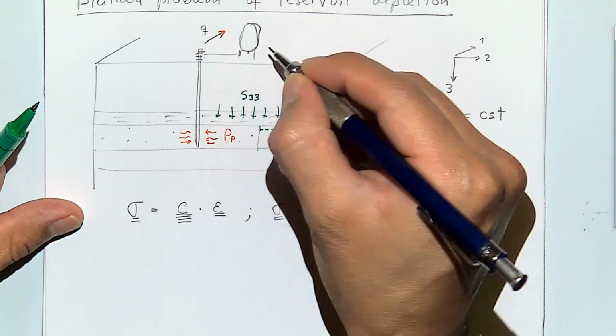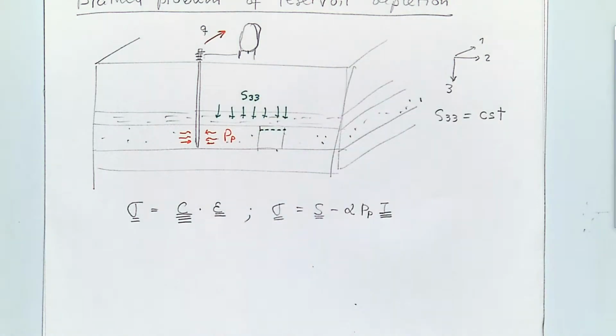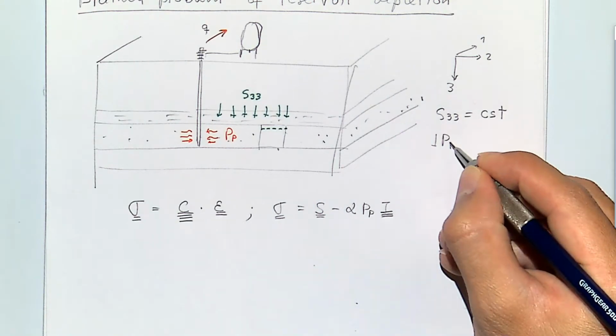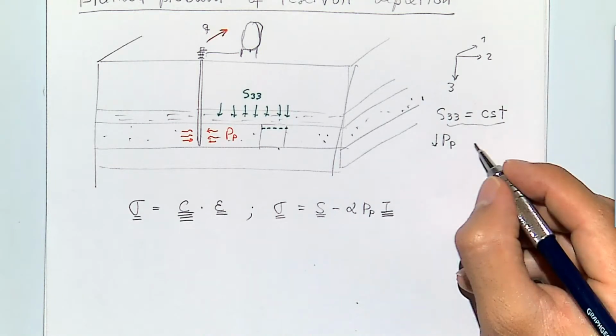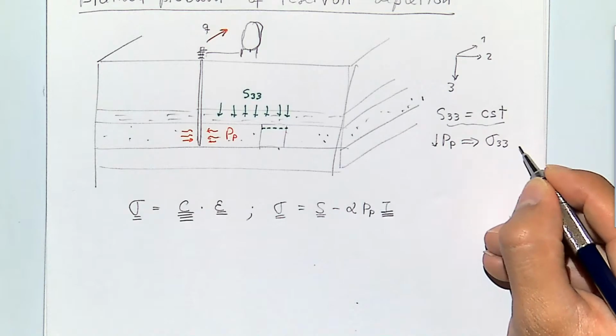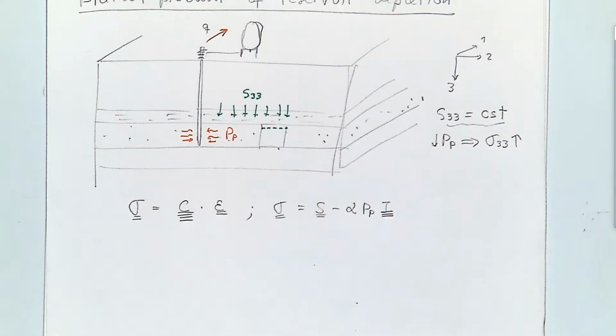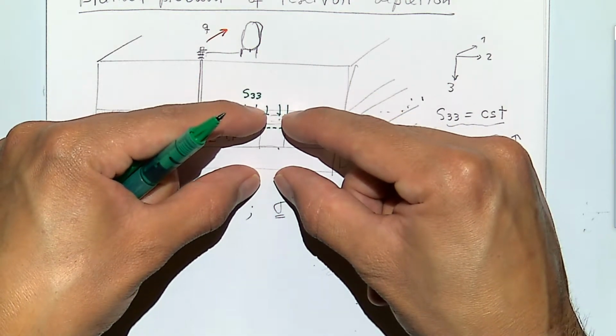Say again, Jack? Why would the rock compact in whatever direction? Because if you're lowering your pore pressure, and if your total stress is constant, that means that your effective vertical stress is going to go up. If your effective vertical stress, I forgot to bring my piece of foam, goes up in this direction, then this one has to squeeze in vertical direction.